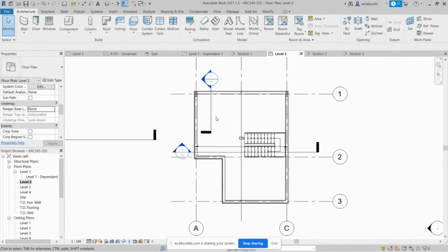This is important, by the way, because sometimes you need to show some items that are below that second floor or the typical floor. But pay attention, if you are doing that and you have a noisy space, or you have lots of details accumulated on top of each other, which is some of the concern that I shared with you, do not always try to avoid the overlapping. So it becomes noisy, and people will struggle to extract information. So sometimes you need it, sometimes you don't need it. So this is now the ground, the second floor shown for me.